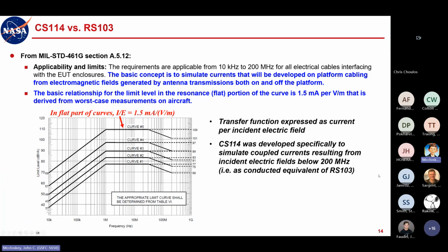To simulate coupled currents resulting from incident electric fields below 200 megahertz. So it was specifically developed as a conducted equivalent of RS-103. And it also applies to cable-to-cable crosstalk. But we primarily relate it to RS-103.